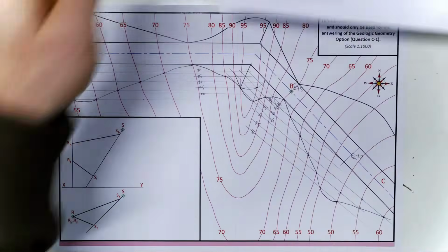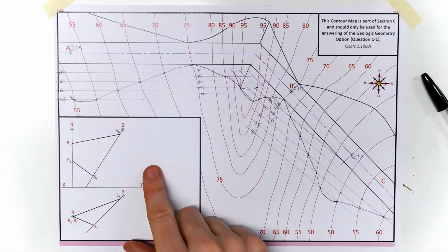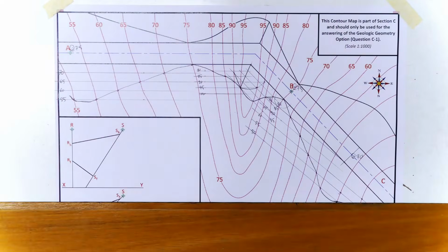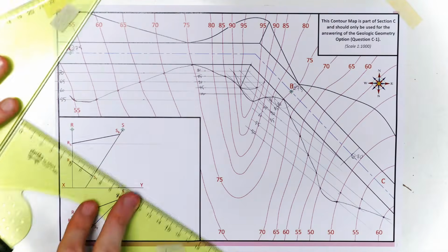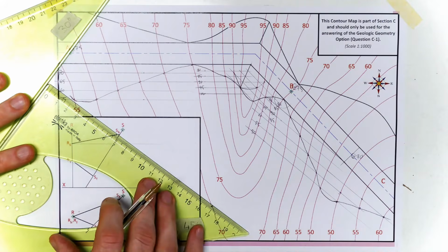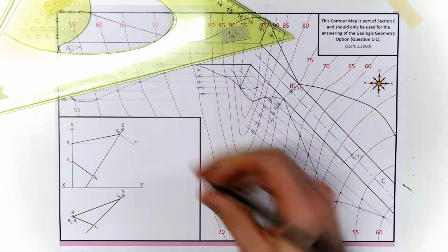So what we want to do is find the top and bottom surface and an edge view of those. Okay, so what we'll have to do is create a plane, and we'll see that edge as a plane. So with this top one, I'll use that. We'll draw a level line, and we'll go parallel to the line on the foot wall from SH. Okay, so now I've created a plane. So this is my plane here.